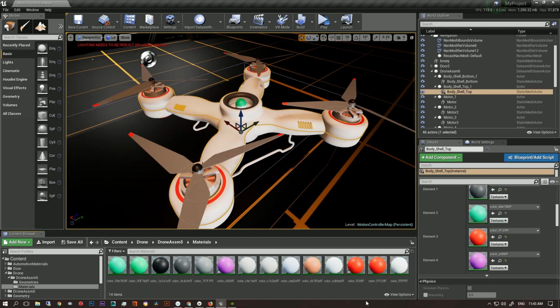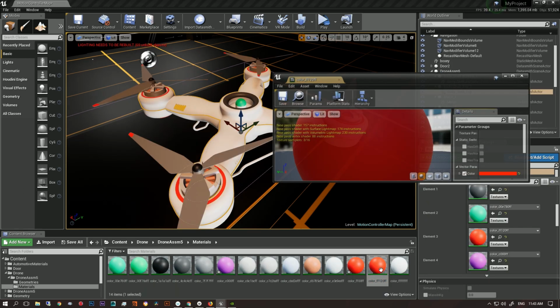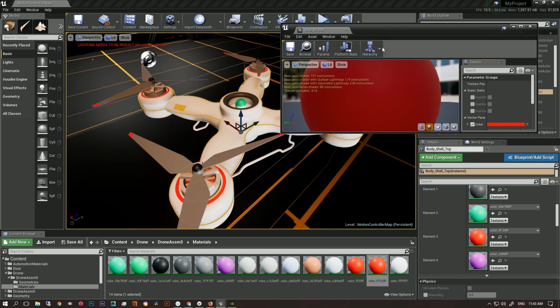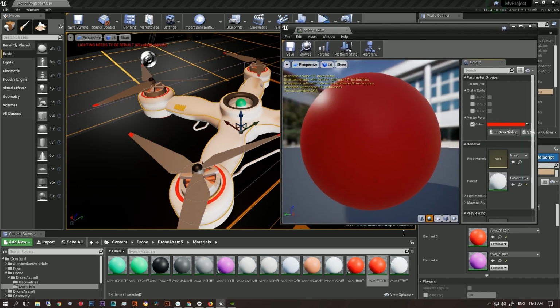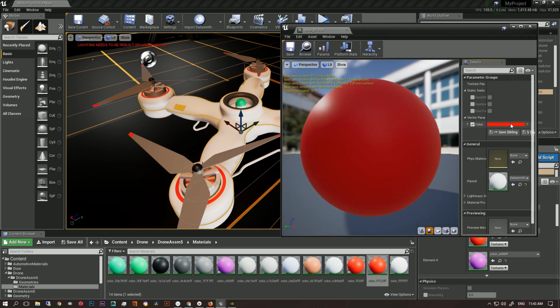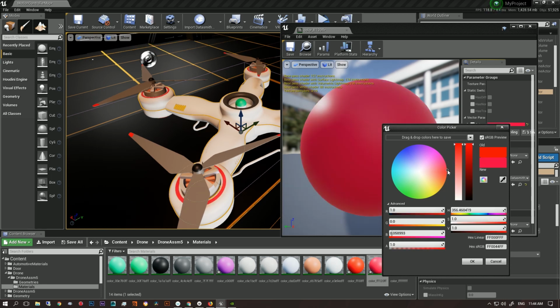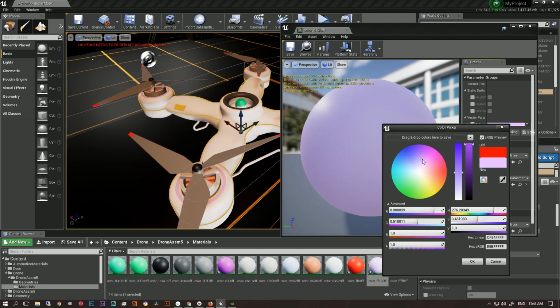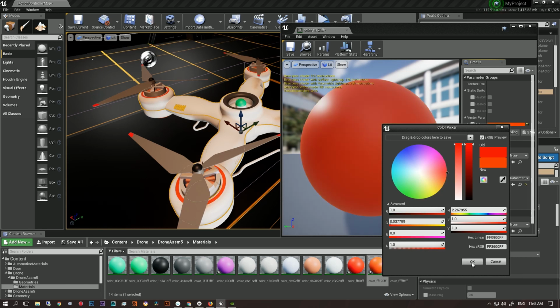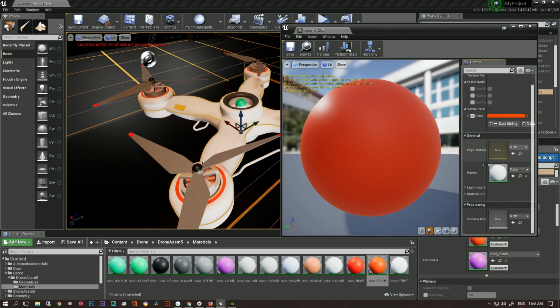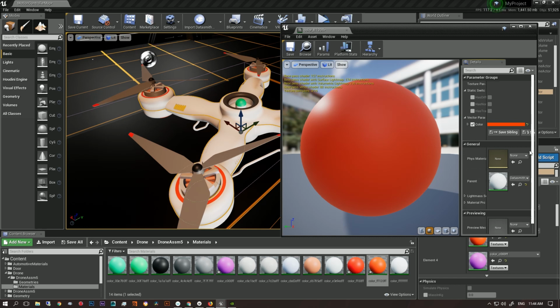Now another really cool thing that we noticed about the Datasmith imports was they maintained some basic characteristics of the materials that were applied in SolidWorks, and they carried over into Unreal. So once you access your shader library, you notice that there's some basic shaders that come in with the import. Now you can either build up these basic shaders, make something that's more photorealistic, or you can load up a preset library and reassign new shaders to these areas.